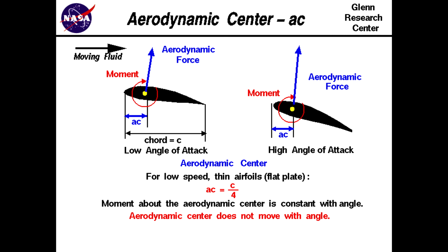The most important point is to put the origin of coordinates exactly at the point where you would like to measure the moment. Then you do not need to do any additional operations to recalculate the moment coefficient. So the moment coefficient you receive is already at the quarter chord.